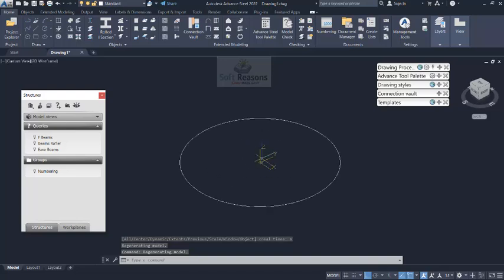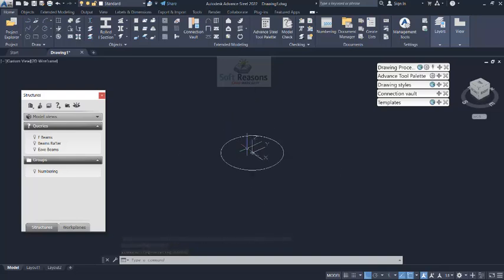Having done this, we need a line. Type L on the keyboard, Enter to have the line, and then the origin as 0, 0, 0, Enter. Go to the X direction, and have that to be 3000 millimeters, and Enter. Escape that, Enter again, line 0, 0, 0, Enter.